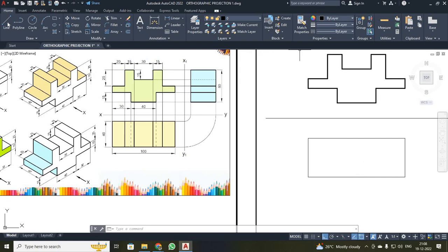Now once again I am going to click my line. I have to draw this line. For that I placed my mouse over here. You can see it has changed to a green color. I am moving towards your downward direction. You can see a construction line coming towards your diagram. Can you view it? I have made it and I have clicked over here, and I have joined to this point.